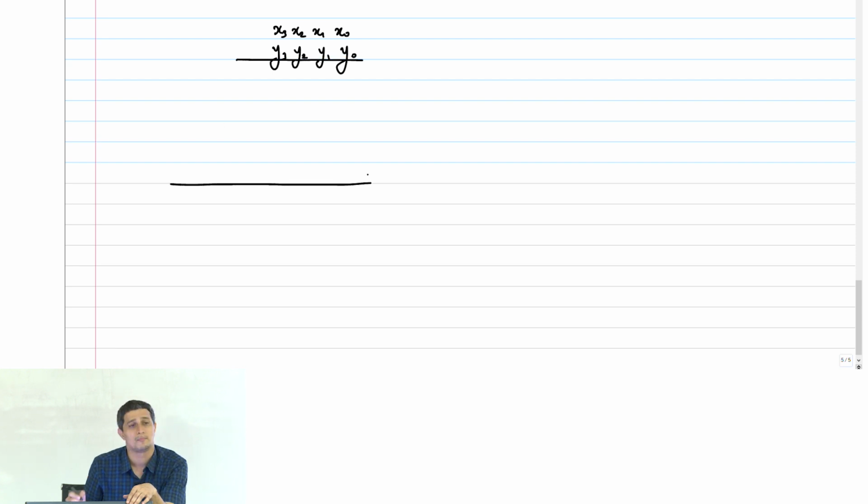So now let us see what we have to do. Suppose I take x3, x2, x1, x0 and y3, y2, y1, y0, and I tell you both these numbers are 4-bit 2's complement numbers. Okay, x0y0, x1y0, x2y0, x3y0. Right? Then I shift and add.